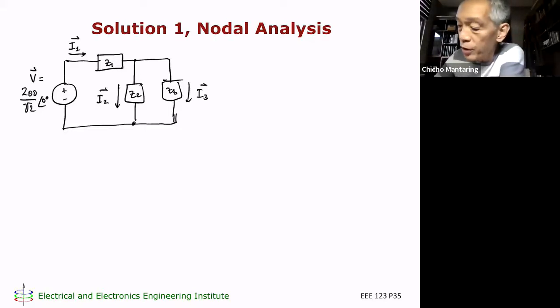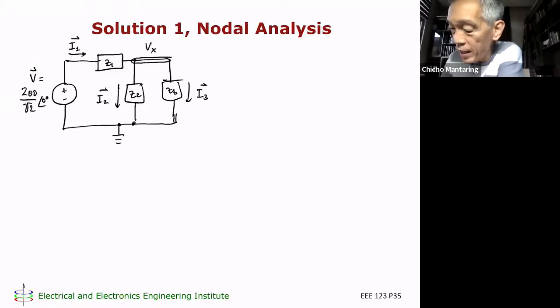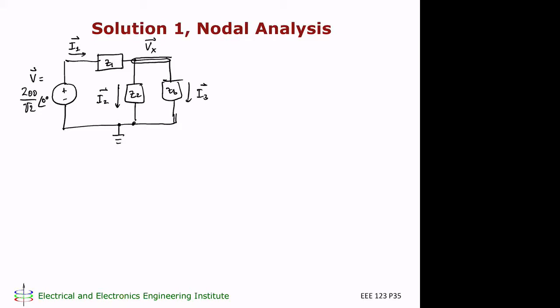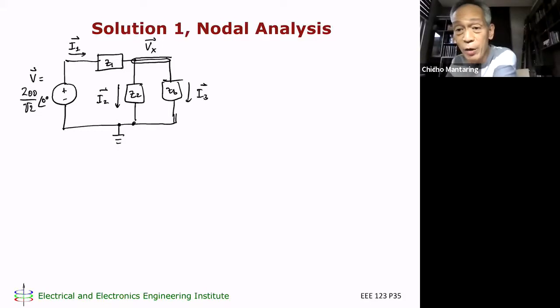The solution I will use here is nodal analysis. For nodal analysis, I will make this my reference, and for this node, its node voltage I will call Vx.